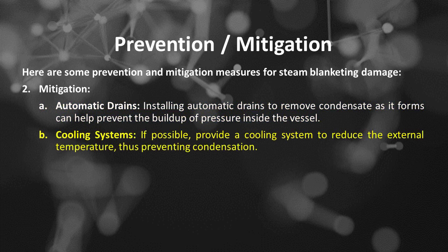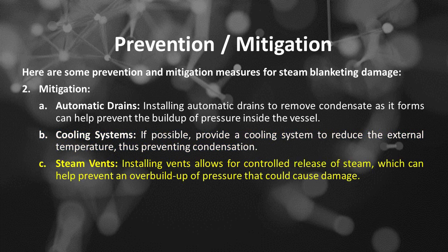The second is cooling systems. If possible, provide a cooling system to reduce the external temperature, thus preventing condensation. The third is steam vents. Installing vents allows for controlled release of steam, which can help prevent an overbuildup of pressure that could cause damage.